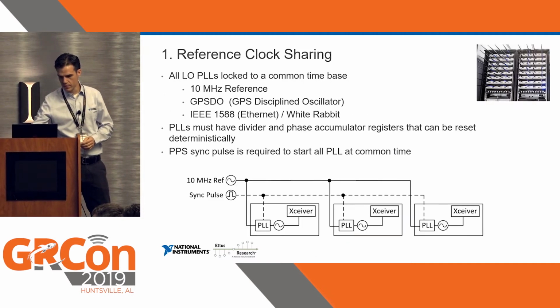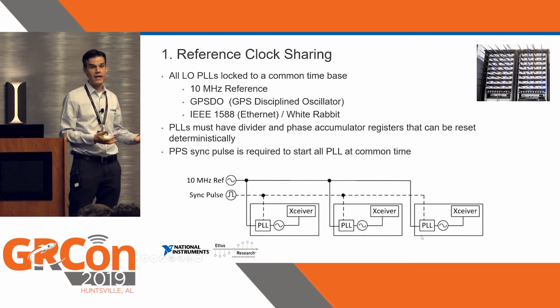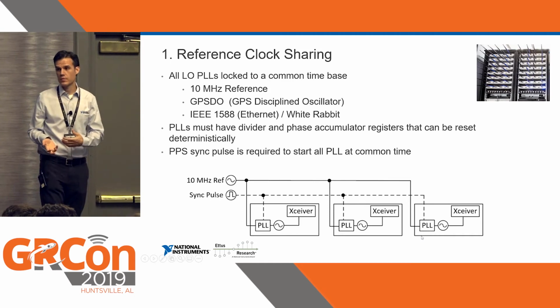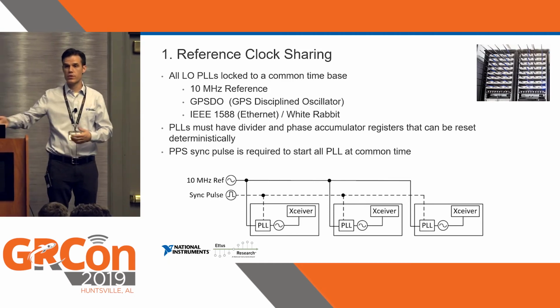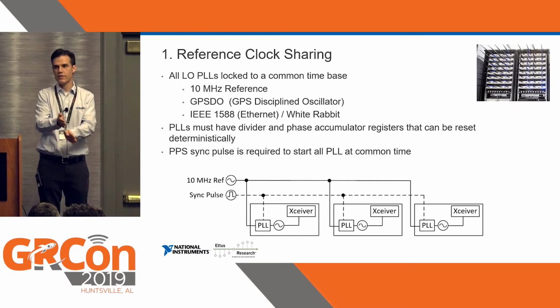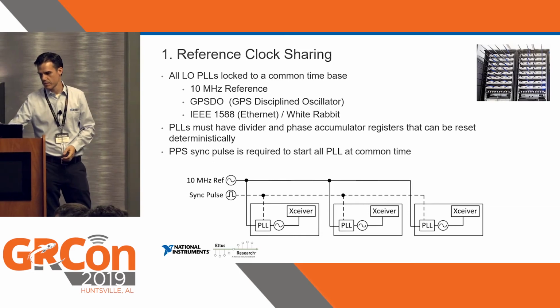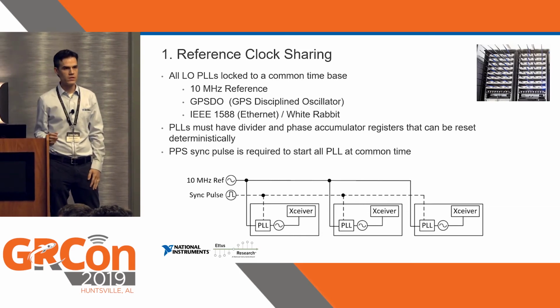And let me go back up one here. You see that each of these devices has their own PLL. And so each PLL has its own phase noise profile, right? They're going to be uncorrelated to each other. So we've aligned the phases of these local oscillators. We haven't done anything to make them coherent to each other in this case. But it is pretty nice because you only have to distribute these two signals.